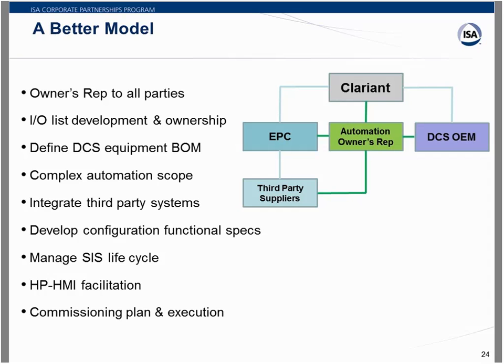Also developing the configuration functional specs. I mentioned that EPC didn't really have the ability to do that in this case. So to come up with functional specs written basically in a language that the DCS configuration engineers could understand and utilize was a big task here.